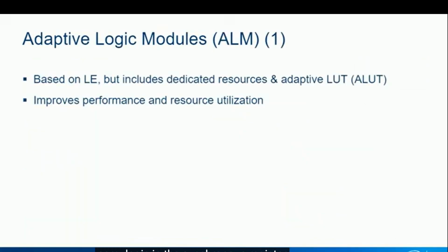While the FPGA LE discussed so far has a definite design flexibility advantage over CPLD macro cells, LE cascading and feedback are still necessary to generate functions with more inputs than are available. To overcome this problem, all new FPGAs use a more versatile logic block as a replacement for the LE called an adaptive logic module, or ALM. An ALM is similar to an LE, but provides some key advantages.